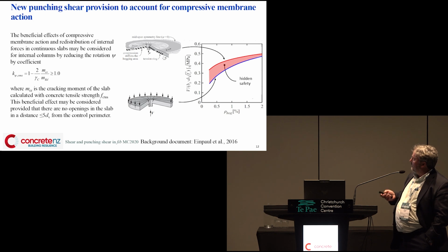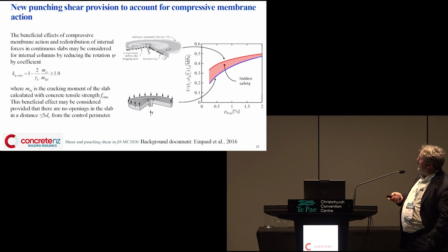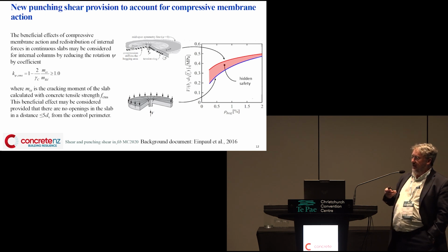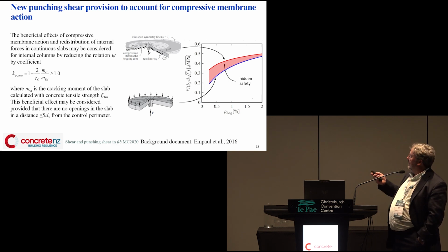All right, I'm not going to go through this in detail because I just notice I'm running out of time. But again, for the punching shear provisions, there have been some updates on that to take into account the benefit of membrane actions for internal slabs. So that's the main change. So you had that hidden safety factor there.